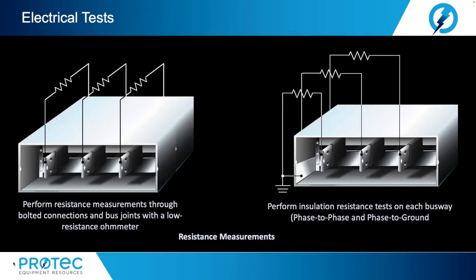Now, we also have perform insulation resistance tests on each busway, phase to phase and phase to ground. Now, this test is going to use something like an insulation resistance test set or megohmmeter, and we're going to look at how good the isolation is between bus bars and frame or ground and between bus bars phase to phase. Again, here we're looking for how well we isolate the flow of current between 2 points where there should be no current flow.